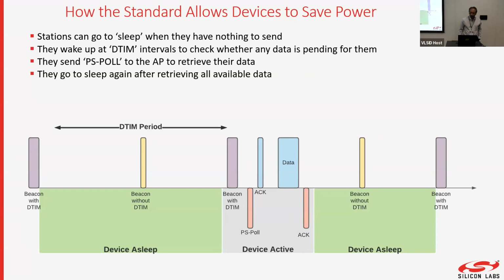After sleeping for so long, how do you make sure you wake up at the right time? If you want to make sure you're waking up at the right time, your clock should be very accurate. It should not drift. Now, the more accurate you make a circuit, the higher current it consumes. It is true for everything. A 12-bit A to D consumes much more current than a 10-bit A to D. A linear amplifier consumes more current than a nonlinear amplifier. Any device that has to work better, there's a cost to pay. Nothing comes without a cost.